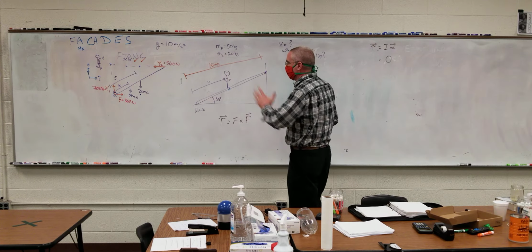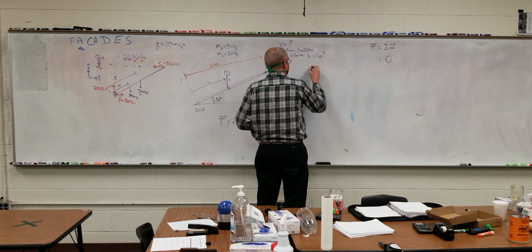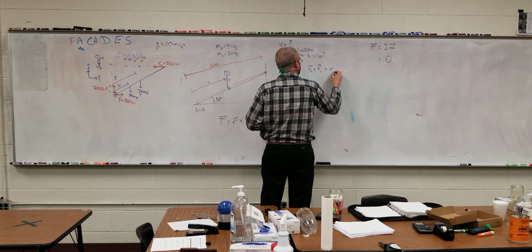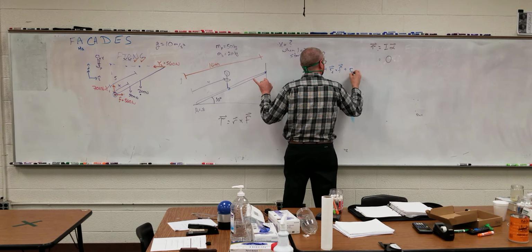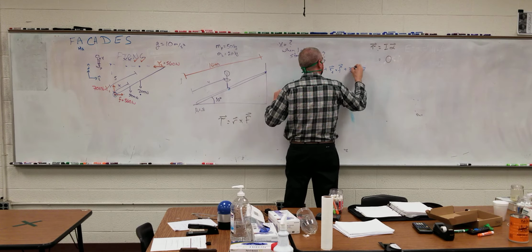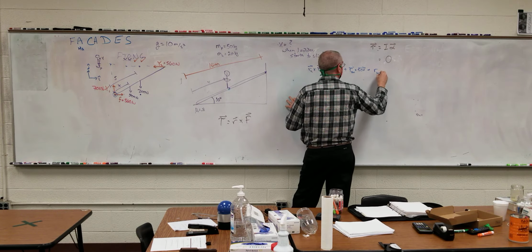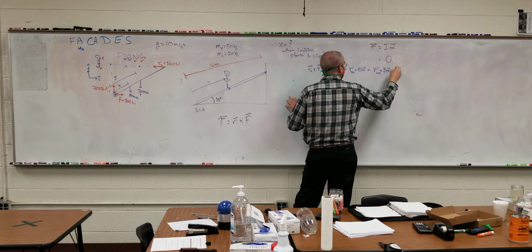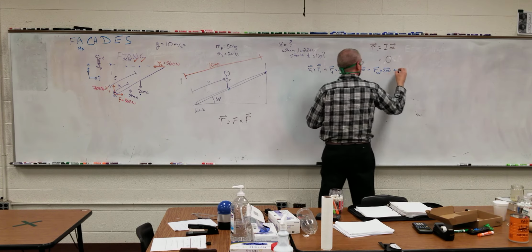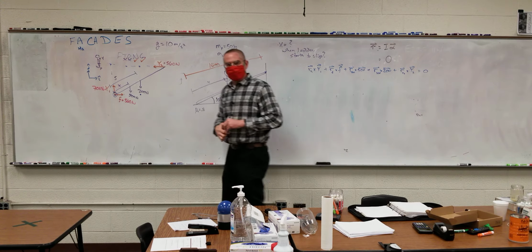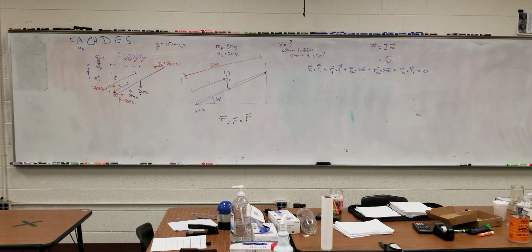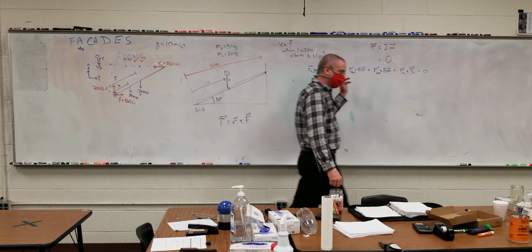All right, so my total torque, I've got 5 forces there, so I'll call it R Y1 cross Y1 plus R friction cross friction plus R 500 cross 500 plus R 200 cross 200 plus R Y2 cross Y2. However you want to label them, I've got 5 forces here, so I have potentially 5 torques. Two of these will be equal to 0.